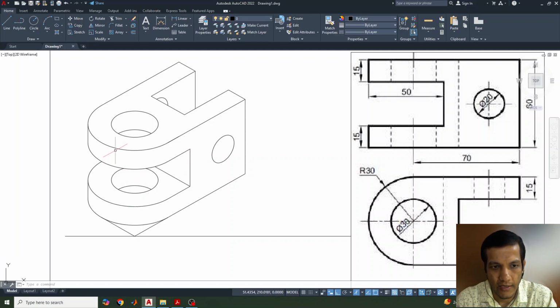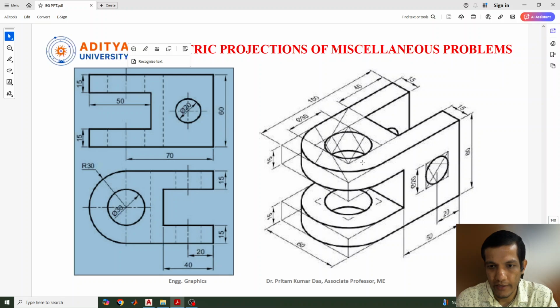Similarly, when you see the object from the front view, we cannot see this curved structure, we can see only a line and this box along with the hole. Similarly, when you see the object from the top view, we can see this kind of shape. This cut portion we can see, along with a circle, where the hole goes through to the last of the object, and there is also a semicircle here. So let's see how the diagram is drawn.